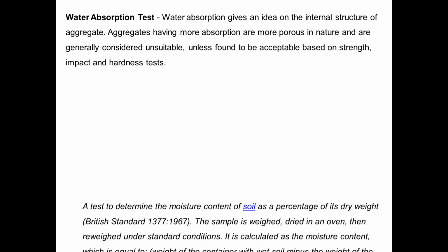Water absorption test. It gives an idea of the internal structure of aggregate. Aggregates having more absorption are more porous in nature and are generally considered unsuitable unless found to be acceptable based on strength, impact, and hardness tests.